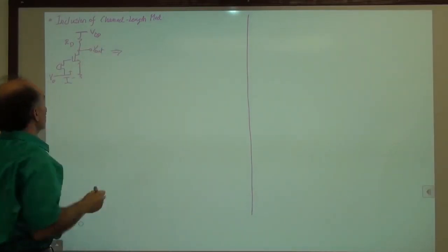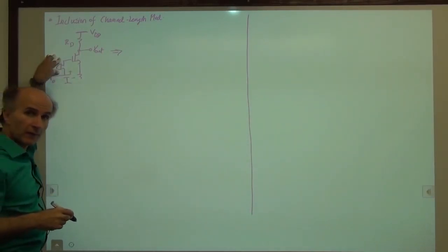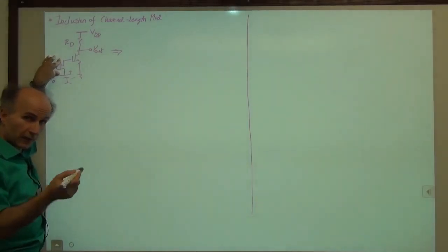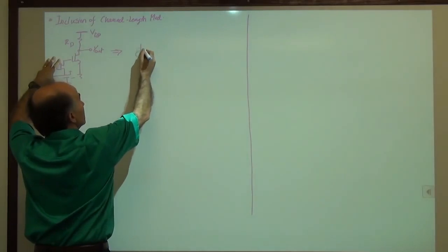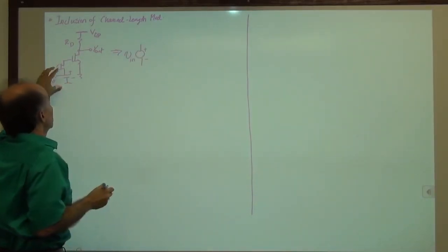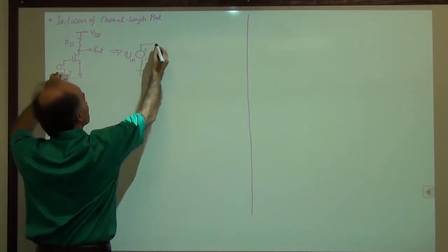So the small signal model is constructed starting from the left. The microphone is replaced by a simple time varying voltage source, so that doesn't get set to 0 because it varies with time. So here's our microphone signal, which we call V in. And this battery goes to 0 because its change with time is 0.